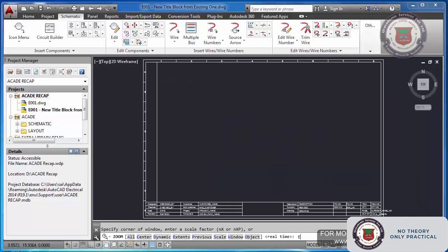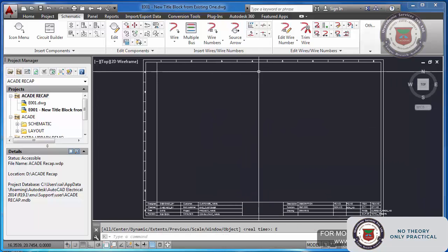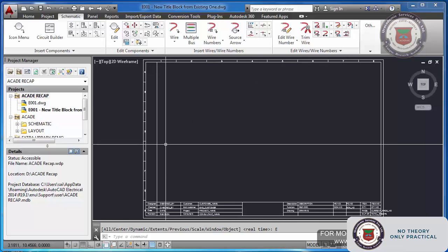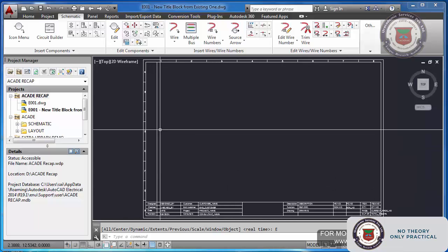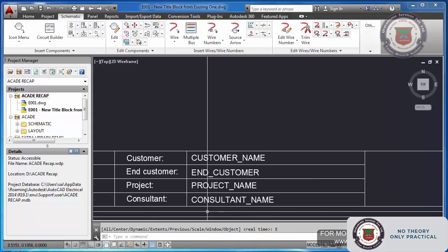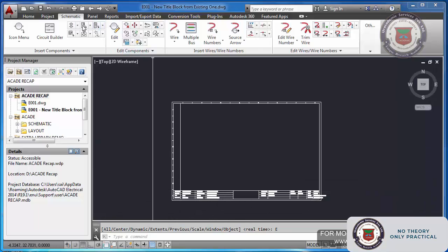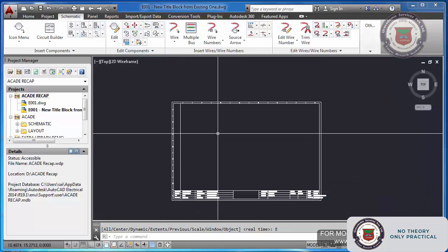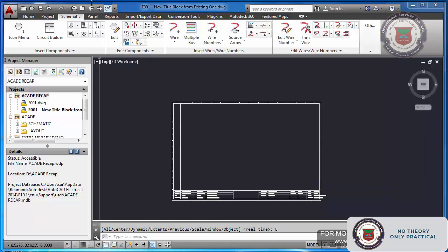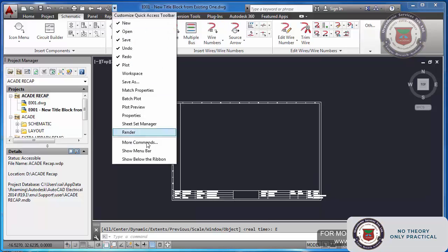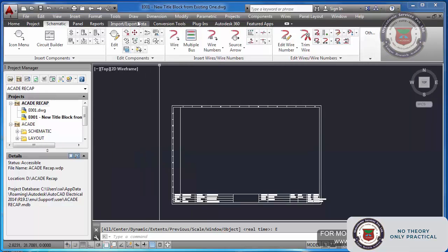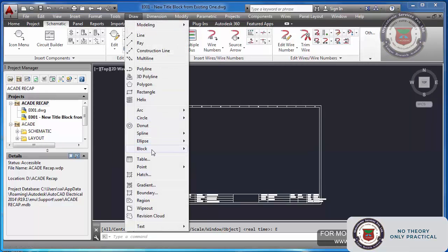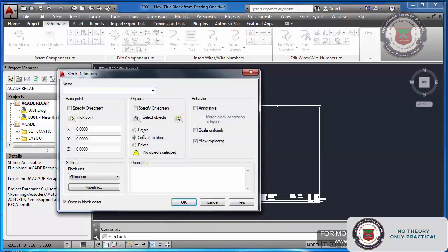So once you have inserted your x and y axis references and set your layer, now again this is not the block, I will change it to the block. For that I have to go to draw and block, but the draw is not here, I couldn't find draw here. So where can I find this? Show menu bar, go here, now comes draw, block, make.